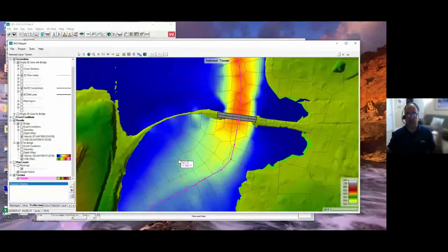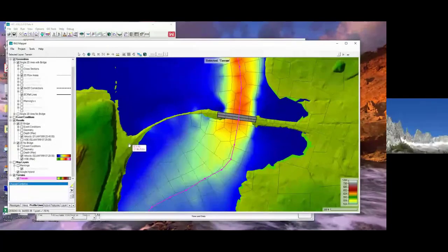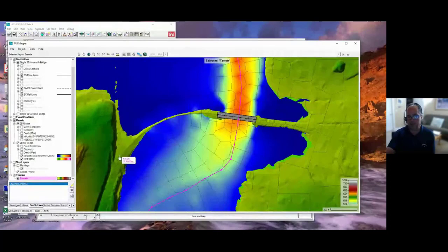I can model it as weir flow, I can model it as 2D flow, I can do breaching, all of those things. Now, there's nothing wrong with making this whole thing one bridge, though. There's nothing wrong with that approach. Okay, but all the losses for everything are going to be wrapped up in those curves then, is the difference. Okay, any other questions?